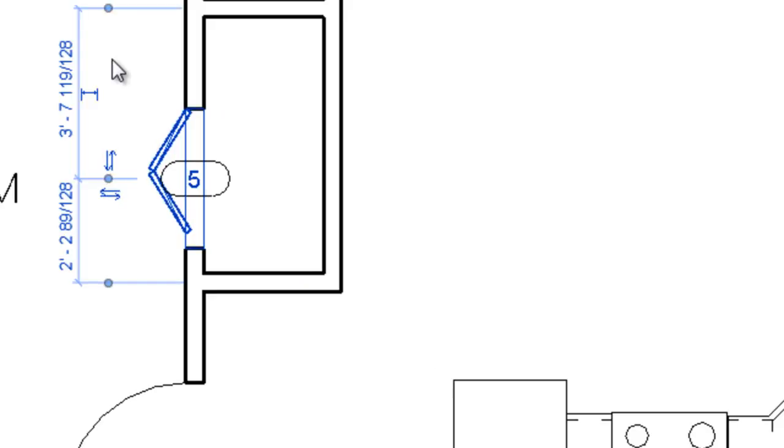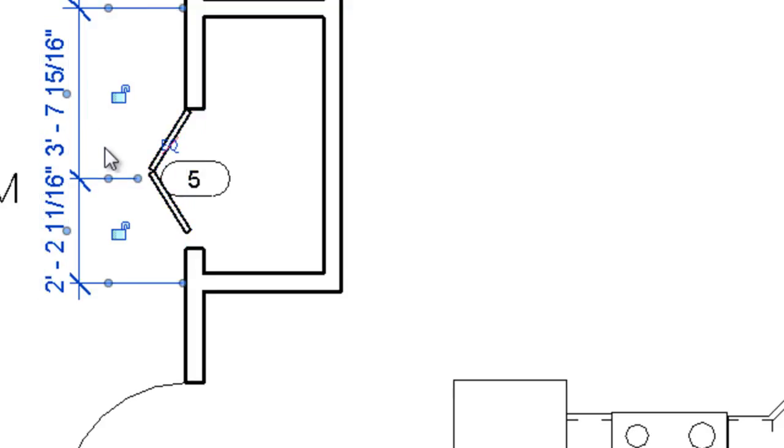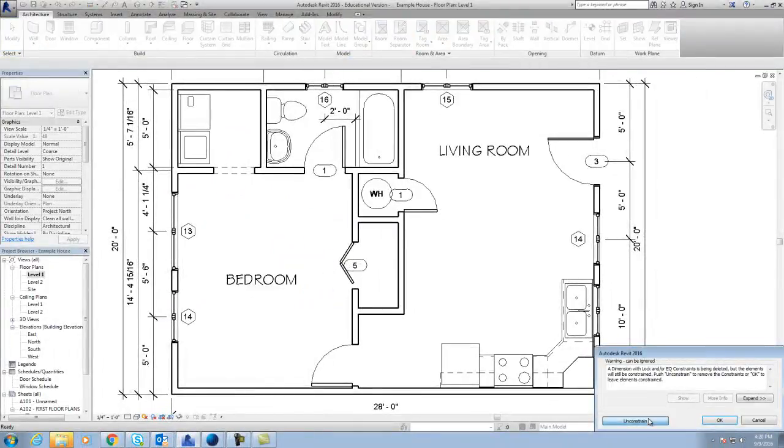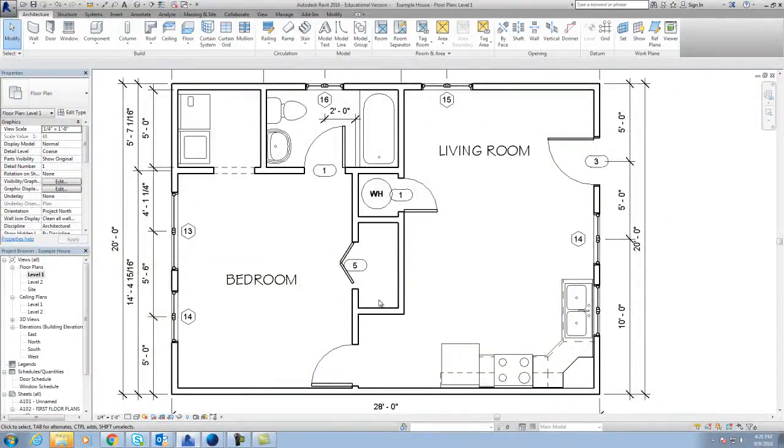You can click that door, hit this little, these are temporary dimensions. You hit this, makes them permanent. Click on it again. You got an equal sign right there. It'll center that door up. So plenty of room for clothes. You got your hot water tank right here close to the bathroom, and it's close to the kitchen, so you'll have adequate hot water as well as the utility closet care center. So, I mean, you have got everything you need here.